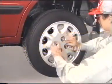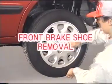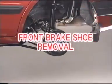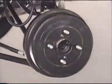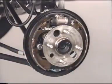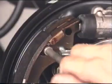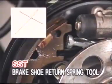Distorted brake shoes, sticking, or oil or grease on the lining could cause brake trouble. The brake shoe must be replaced if necessary. Release the parking brake, and remove the front shoe. First, disconnect the return spring using the SST.